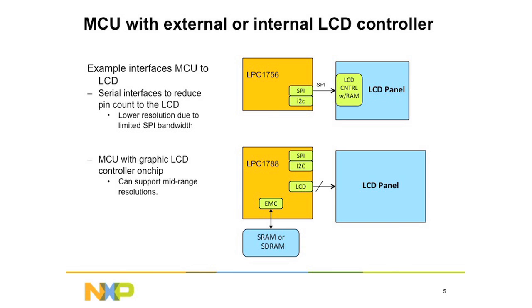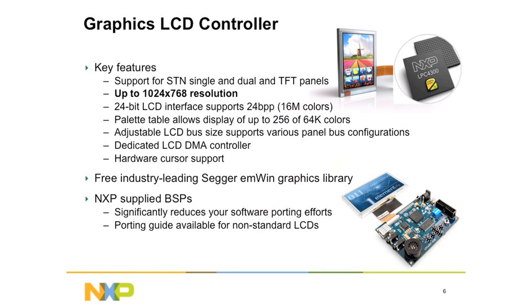Both work well. We have customers using both, but in this space we're going to talk about the idea of having the embedded controller built into the part because it just gives you higher resolution and more bandwidth in terms of some of your choices. You may or may not need external SDRAM depending on the resolution. We have an external memory controller here that allows you to add that fairly easily. You probably want your frame buffer in there if you're doing 16 or 24-bit color. You don't have to. What I didn't show here is there's a new interface that we have, SPiffy, that Vandana will talk about, that allows you to take large amounts of images in an inexpensive space and directly DMA them out to the LCD controller. So you can actually do something along those lines as well.